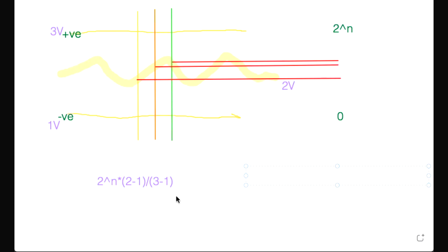All right, so there's method to the madness. The reason I sent you all off to look at that is because I wanted you to understand that A to D converters all have the same principle of operation, even if they have different internals. This is how all of them work. You have a negative reference, you have a positive reference. It catches the voltage somewhere at a point in time. It's going to give you a binary number based on where the voltage you caught is relative to your negative and positive references. That's all it is. It's not any more confusing than that, and that is the principle of A to D operation in general.